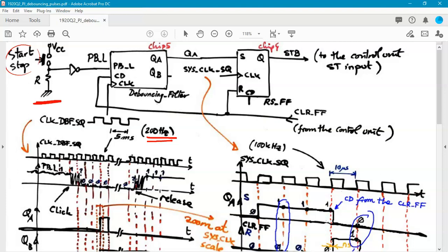If you have to sample voice, for example, you will pick up an 8 kilohertz sampling frequency. Or if you have hi-fi in mind, it is going to be 44.1 kilohertz, the CD quality, right? So the physical phenomena that you like to digitalize is demanding a very specific frequency.